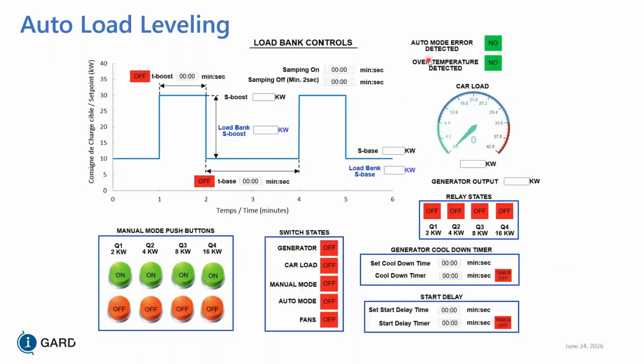So this particular customer wanted us to put a load profile that looked like this. So this time here was variable. This time was variable. This step was variable. So with an HTTP page, website, we put it into the load bank, you put in all the parameters, and it would be running along, and this is your minimum baseline.